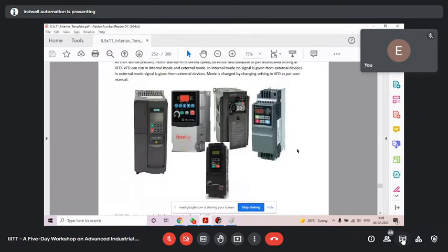See, these are AC drives of different brands on your screen. So an AC drive will look like this. Its size will increase. This part you see is your heat sink. Behind every AC drive, you will have a big heat sink. You can see you have a display and some keys. Through this, we operate it and do some settings. And when you remove this cover, there you have terminals to give power supply, terminals for the motor, and digital input output, analog input output terminals.